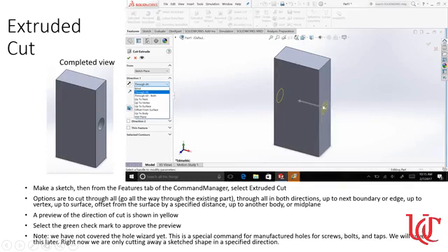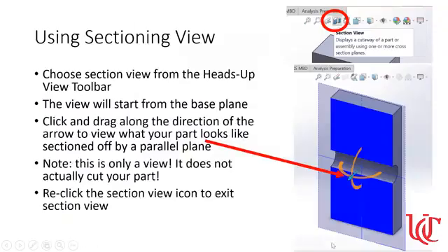Again, right now, if I wanted this hole as a circle kind of cut through, I'm not using hole wizard, I'm using actual extrude cut here. We'll learn hole wizard is a special command for when we're doing things like screws and bolts. Later on, we'll learn that.